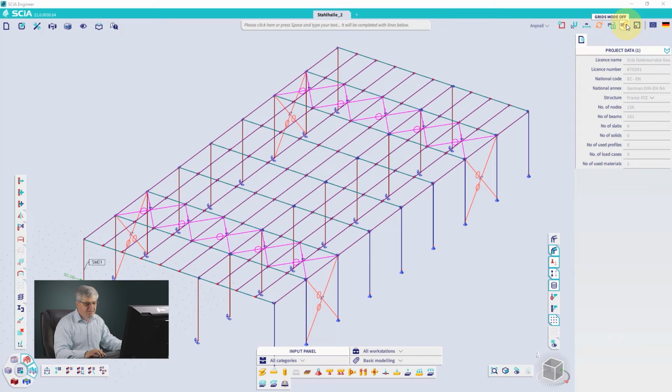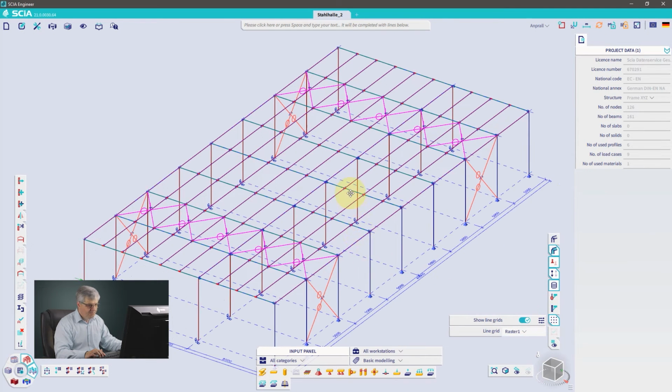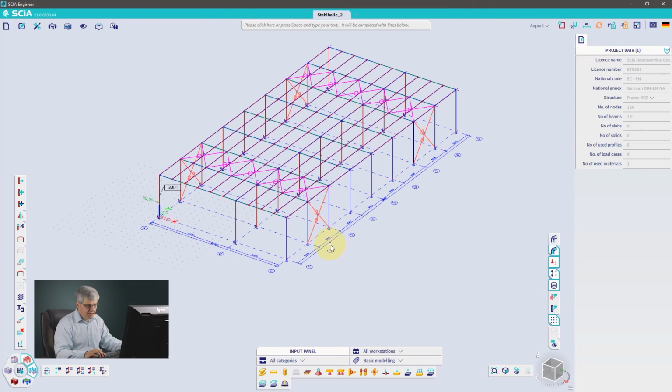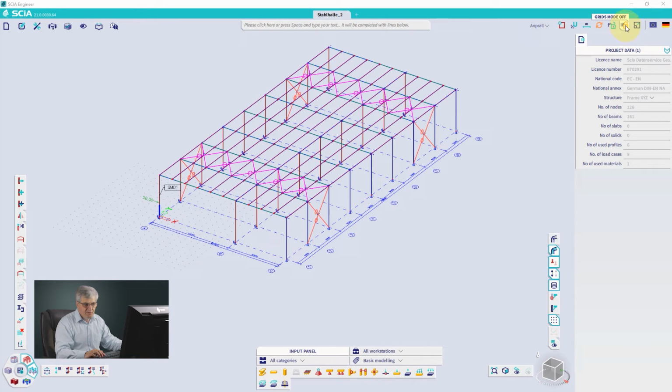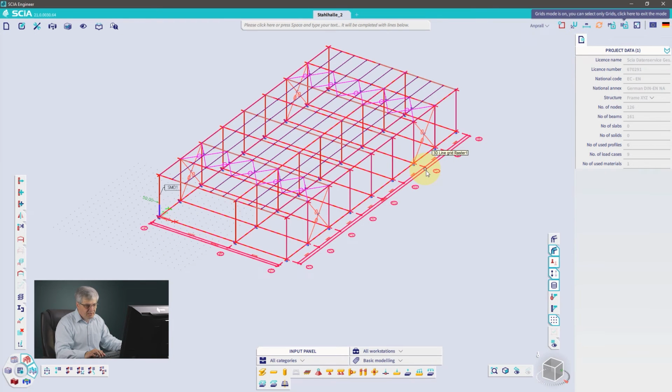And then is the grid mode. So I go here and activate the grid, and I want to change the grid. I cannot activate it and cannot change it because it's hidden. It's only for the snap points. In the old user interface there was menu, grid and stories, 3D grid and stories, but no, it's not there. So if you want to go to grid, you have to activate this grid mode. You see this text, then you can click on your grid.